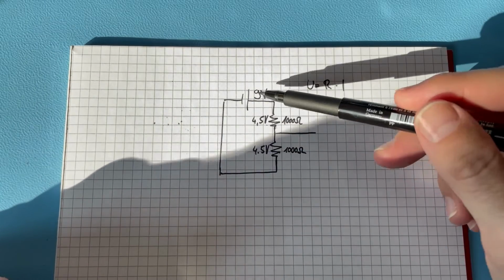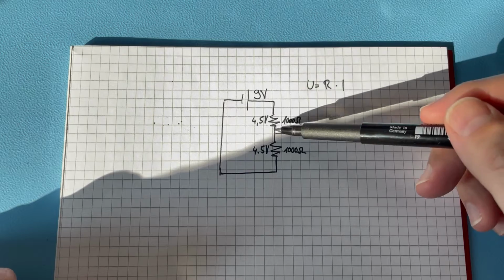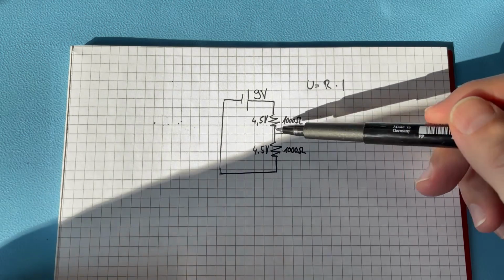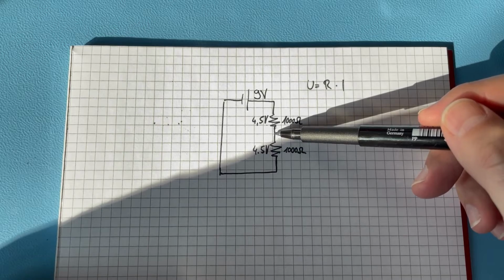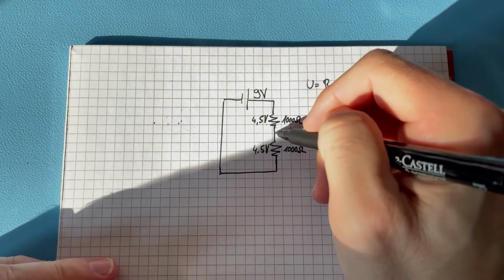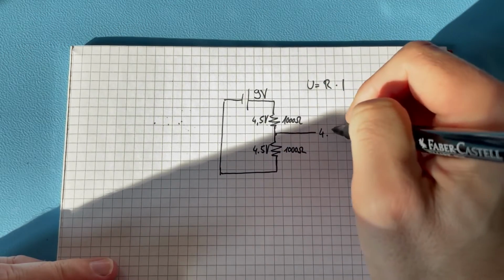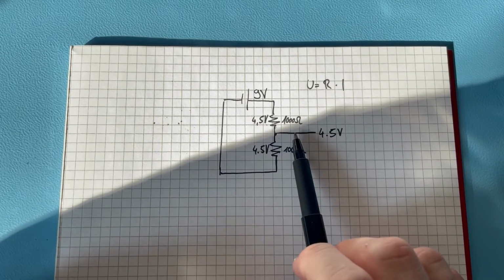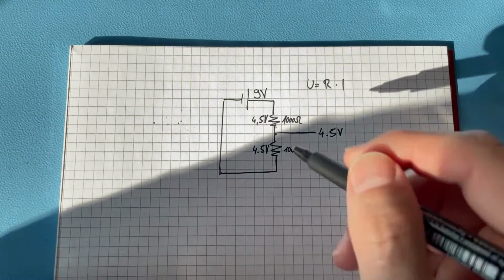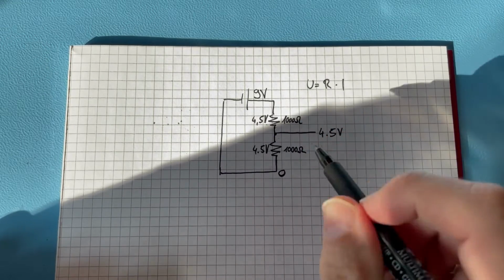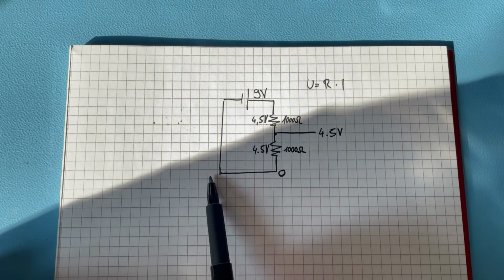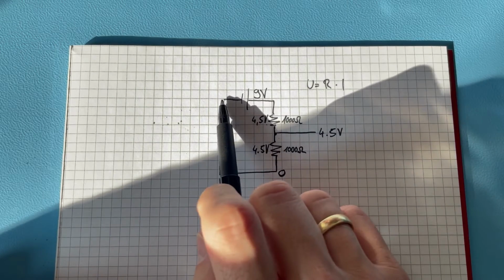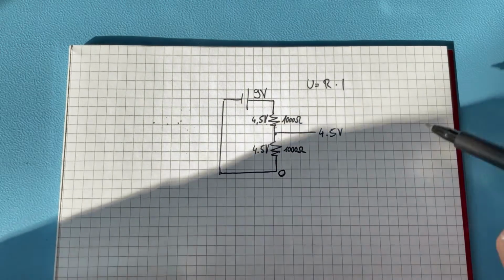And that's a voltage divider. So we split the voltage in half. We lose from 9 volt 4.5 volt to here. So where are we left with at this point? Yeah, we are left with 4.5 volt here. And then we lose another 4.5 volt from here to here, and we're left with 0 volts. And no wonder, that is good, because you really are directly connected to the negative terminal, to 0 volts, and that's really what should happen.